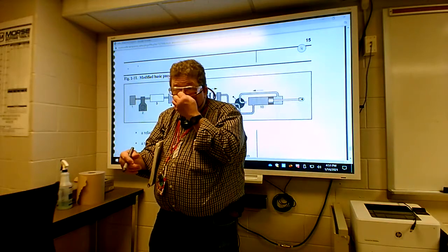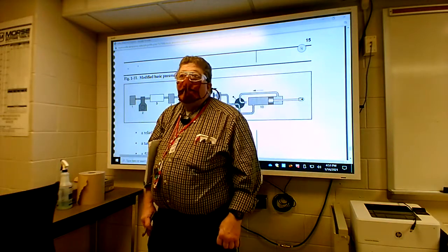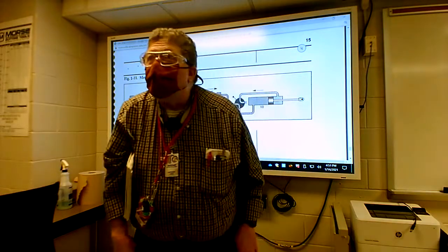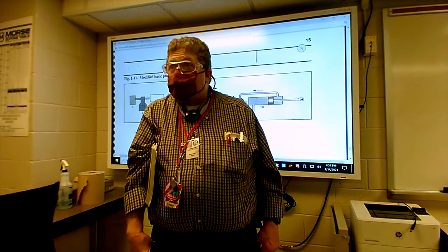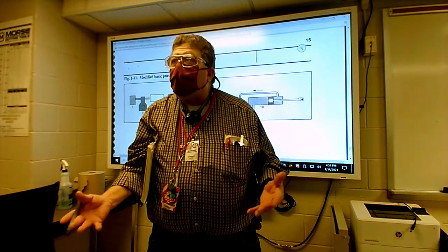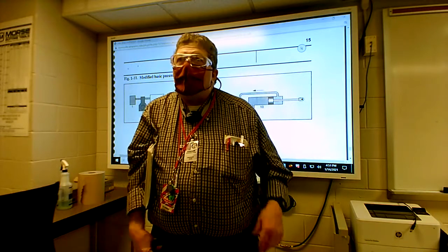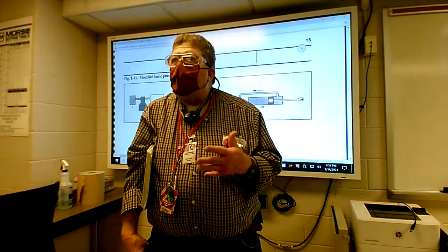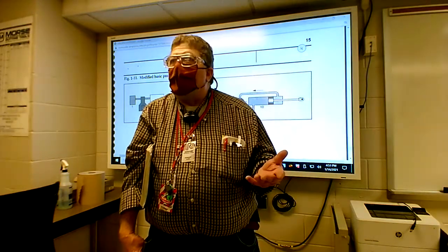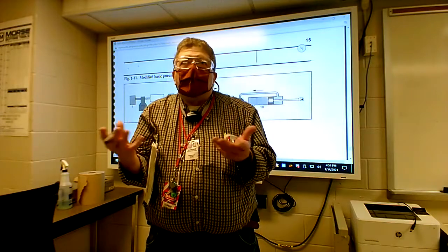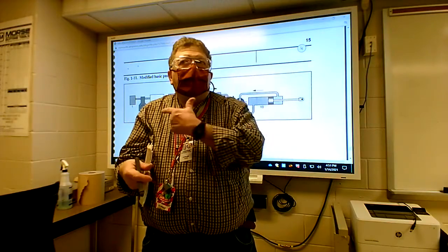Do you have the intake filter on your vehicle? Absolutely. When's the last time you had it checked? Right. So if you know that, what happens if you go 2 years or 3 years and don't change the intake filter? Then the vehicle starves, right? It's not getting enough air, so it affects the performance of the motor, right? So when you pull it out, what do you see? You get contaminants, right?